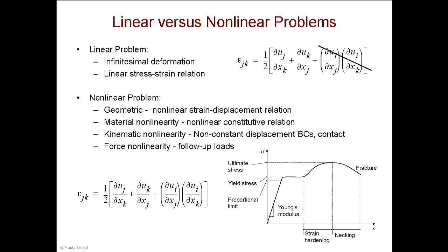But if the stresses give you a huge stress compared to the strength of the material, it may be worth doing a little more homework, putting in the nonlinear stress-strain curve and studying how that stress concentration behaves. Because now you're going to properly account for the plasticity at the hole, and the stress distributes much better at the hole than it will with a linear analysis.